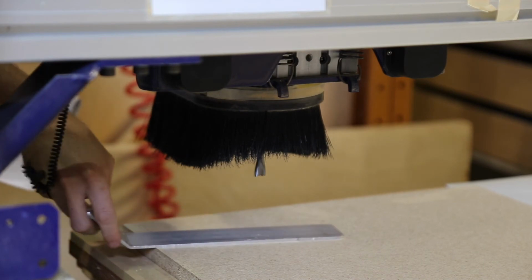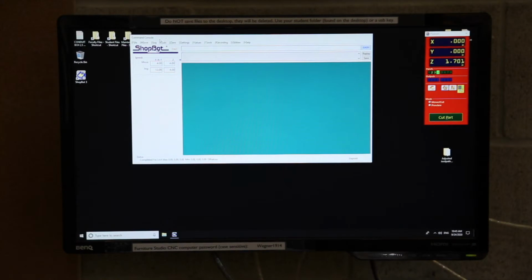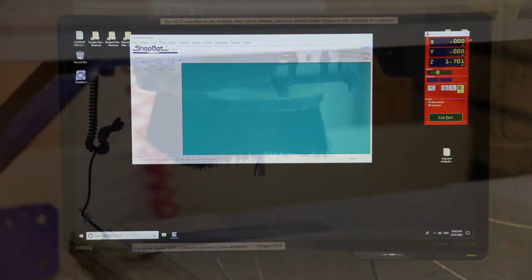Remove the aluminum zeroing plate from its plywood holster and place it under your bit. In the Shopbot 3 control software, enter C2 in the command line or click Cuts and select 0 Z axis with Z0 plate, or select the same function directly from the red position pane.